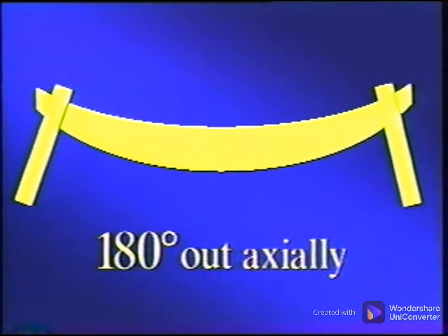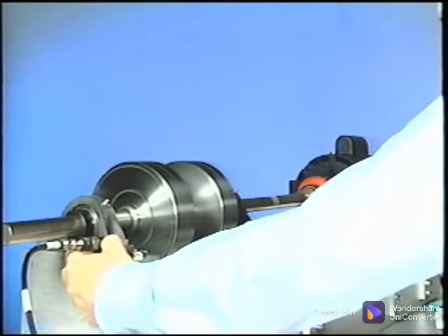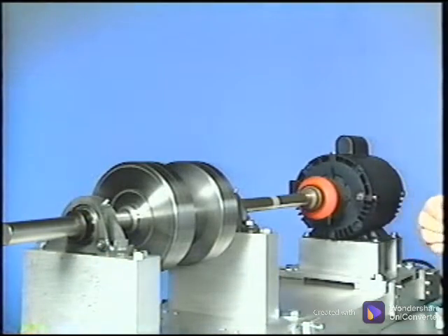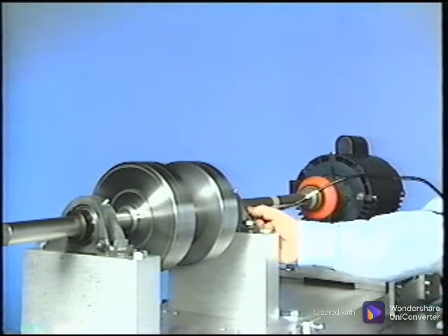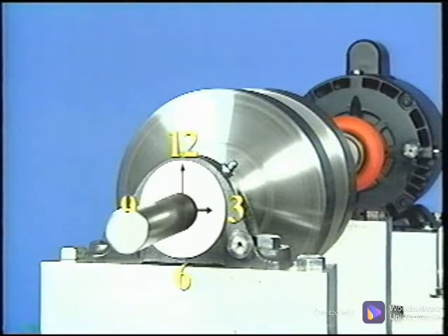Be sure to account for the direction of the sensor. Because of the axial movement associated with a bent shaft, the axial direction provides the most information. 4 other axial measurements should be made. Assuming a clock face over the end of the bearing or machine, the measurements should be made at 12 o'clock, 3 o'clock, 6 o'clock, and 9 o'clock positions.